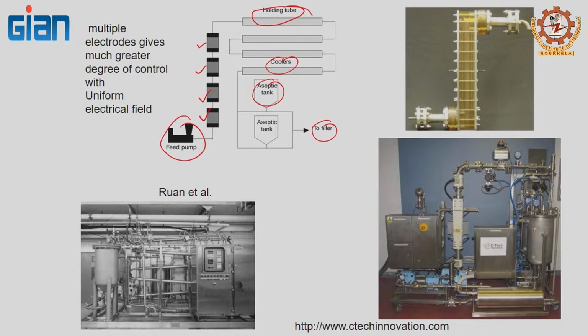So you go to stage 3, and you increase the temperature further. At a higher temperature, say 75 Celsius, the electrical conductivity becomes higher still. That means the electrical conductivity value and the temperature are coupled with each other. As the temperature increases the electrical conductivity, more current passes, which increases the temperature further, and so on. This is the reason for a controlled temperature increase. They probably have 4 heaters so that they can modulate the temperature increase in a controlled manner.